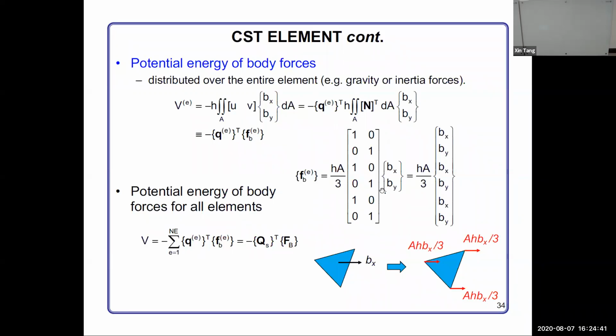So this kind of calculation actually tells us that if we have a body force Bx applied throughout the body, that can be equivalent to one final force applied at the center of mass of the element, that equals Bx. And the unit of this Bx is Newton per volume. Okay, Newton per volume, or sometimes the unit can be pound per inch cubed.